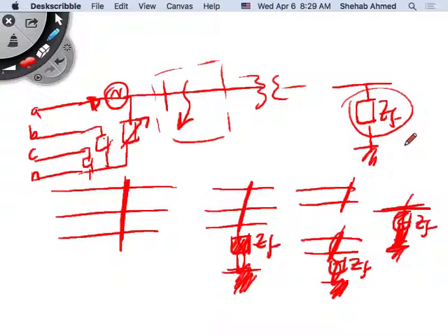This load can be smaller impedance or higher current, all the way to zero impedance, right? Zero impedance would be a short circuit. Somebody took a copper bar here and connected the live and the neutral together. This is a short circuit, right? This is one kind of unbalance.